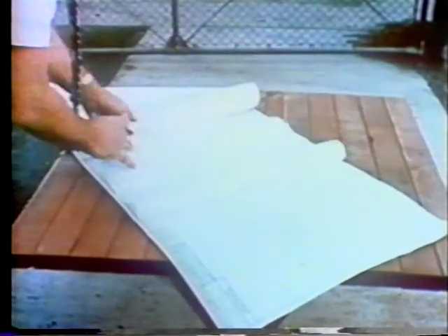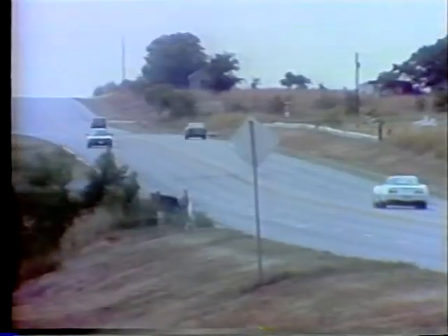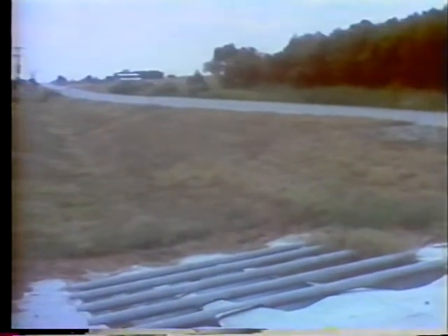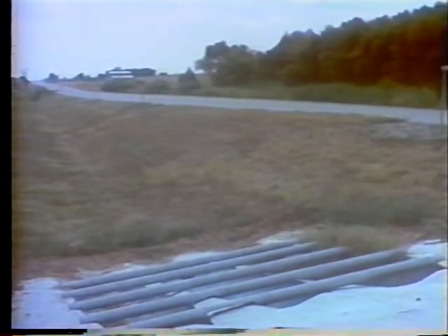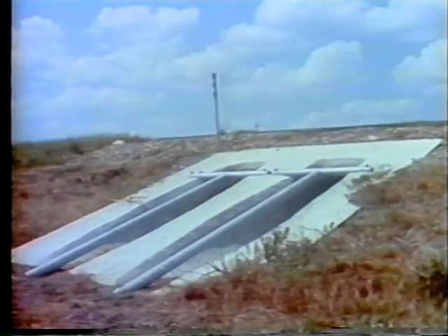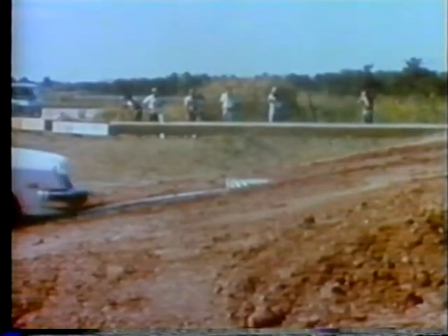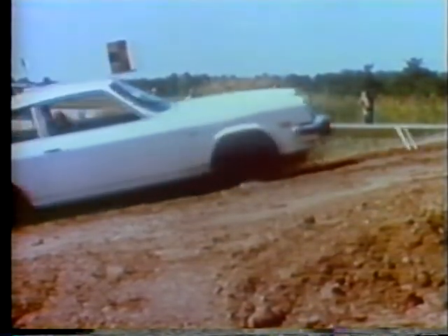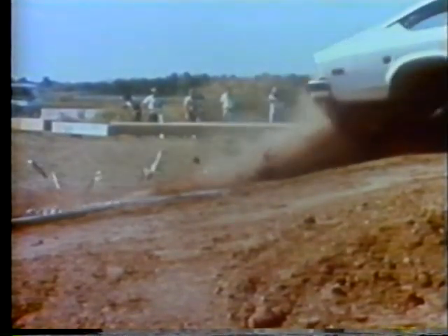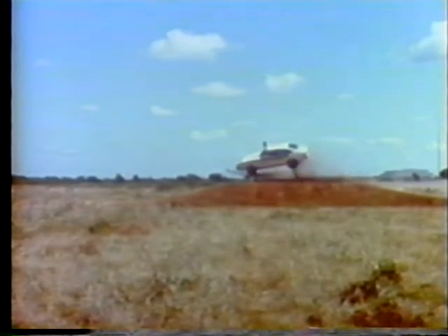Many things are considered in the design of a safe culvert end treatment besides water flow and volume. Among them, the approach direction and departure angle of an errant vehicle relative to the end of the culvert, the steepness of the side slope around the culvert, and the size of the culvert opening. The size and shape of the culvert determine whether a vehicle's wheel or bumper will snag in the culvert end.